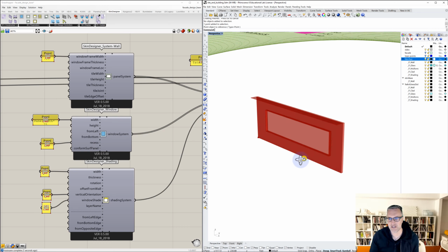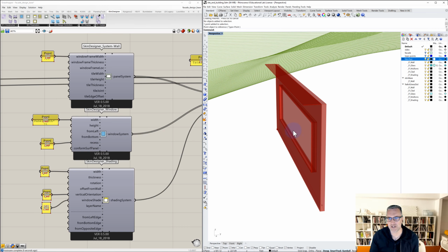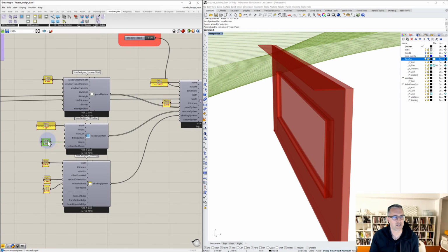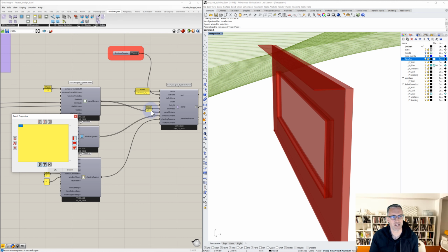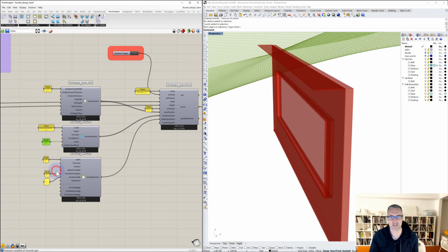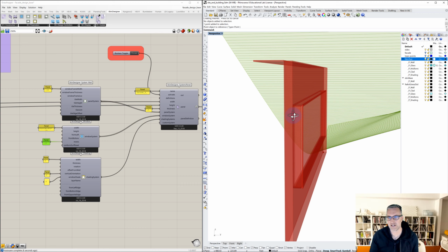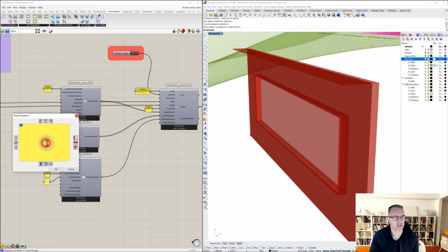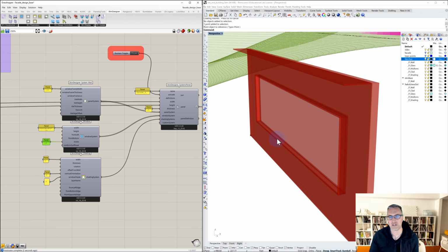The recess is just where the glass is located in relationship to this. So let's set this to be, we know that our full panel is 0.5. So let's set the glass at 0.5. We can see the glass moved all the way back to the inside, but maybe a little too far. Maybe we'll set this to be 0.4. And so we can have that set all the way back, or let's see if we say 0.